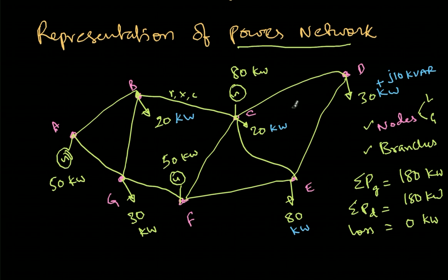But one point you should know is that this transmission line will have a significant amount of reactance themselves. So a good amount of reactive power is also consumed by the transmission line. But it's okay, because for reactive power you don't require any fuel to generate it. Active power you require fuel. For reactive power you can generate it through other means, reactive sources, or going for over excitation of the generator, and so on.